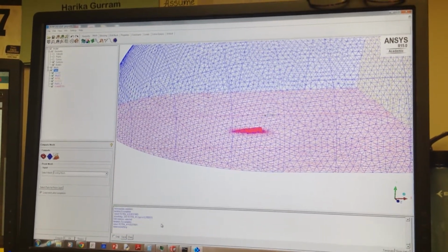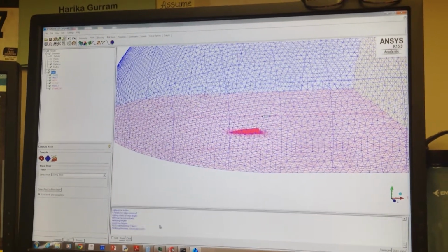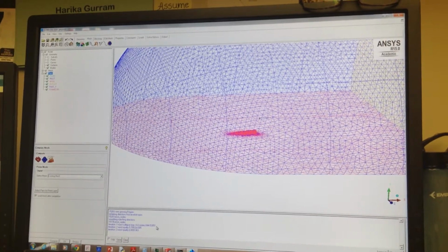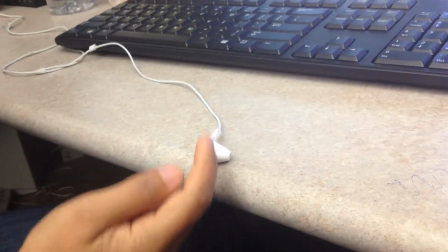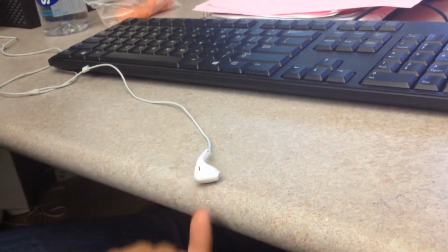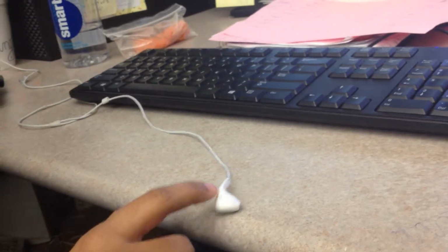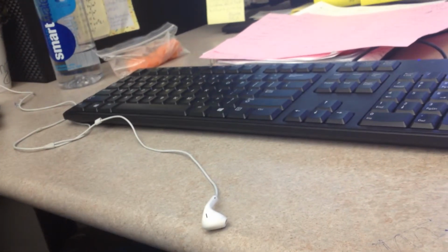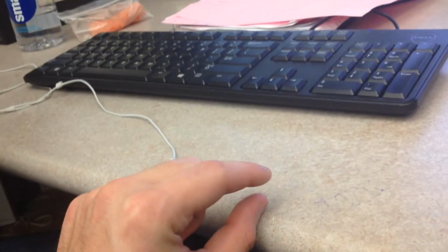So when you change it down to 5 from 10 layers, what is that doing? That is inflating. Like you have a wall, you're creating a volume mesh, right? It's inflating the mesh from the wall to the cell, covering the boundary layer. So instead of 10 layers in that boundary layer, it's only 5. Yeah, but it's a long process.